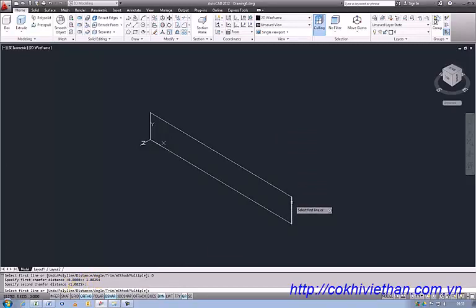We just need to select our lines, so we select our first line here near to the apex of where we would like to put the chamfer. And once we've selected it, we need to hit enter, and now it's asking us to select the second line, so we'll select the other line, and there we have it. We have put a chamfer on it.